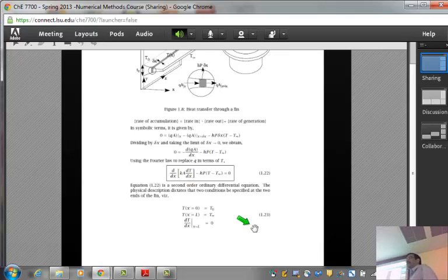Is it linear or nonlinear? It's linear. Why is it linear? Because the unknown is T. The unknown is the temperature distribution as a function of x, T as a function of x. So if I say k is a constant, then it is a linear problem. Now A could be varying as a function of x. Does that make it nonlinear?